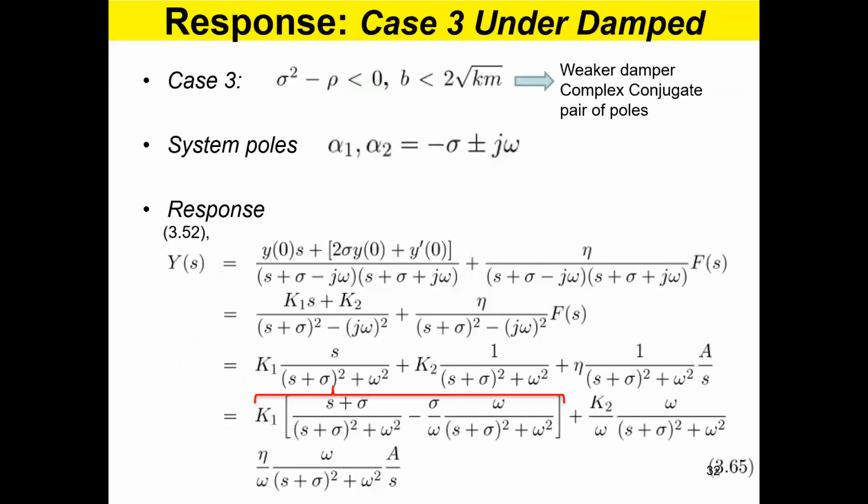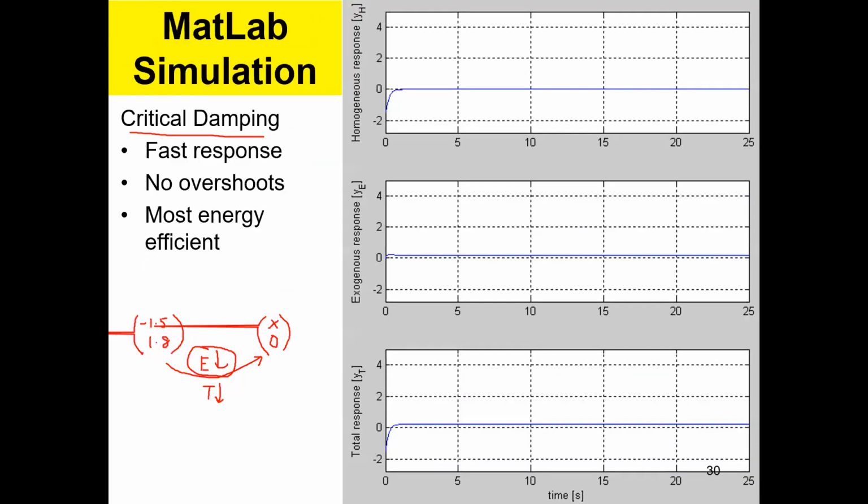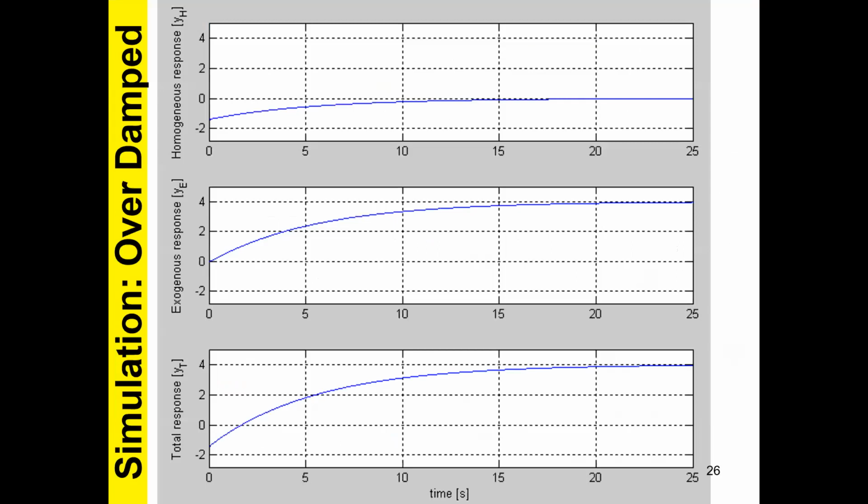So the first one, this response, it squeezes about 4 centimeters. That's, I think, a bit too much, and it doesn't have any oscillation. It takes about 20 seconds to complete. Do you agree with that? Is this a good design for a shock absorber?